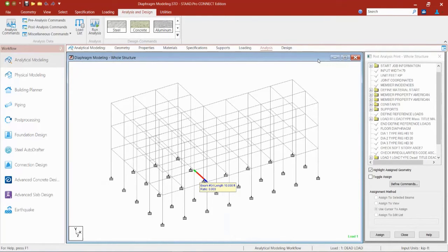In addition to that, if I have, say, a re-entrant corner, I may want to consider adding some notes to my drawings or some extra detailing information about detailing collector elements or fastening of my deck to my structural system. The final thing I may also want to consider is if I did have a torsional irregularity, I may need to adjust the accidental eccentricity that I'm applying to my seismic forces. I may not want to just consider 5% eccentricity. I may be required to scale that up depending upon what seismic design category I may be in. So this information will help you when you get to the next phase of your design, which is planning how to generate your seismic loads on your system.